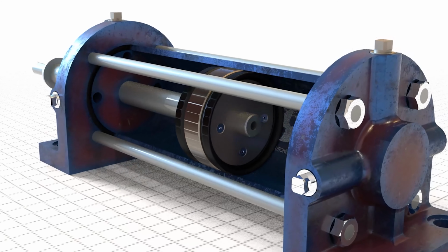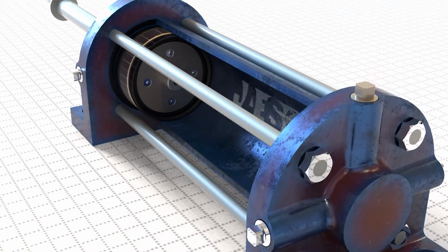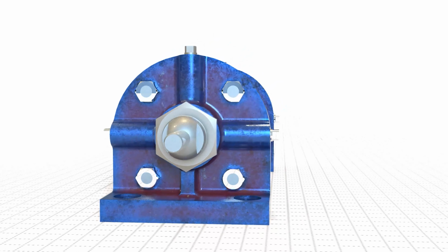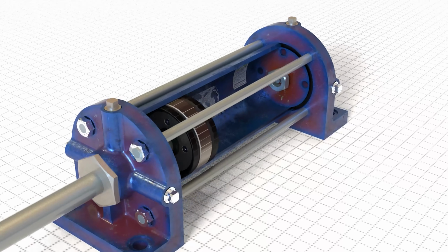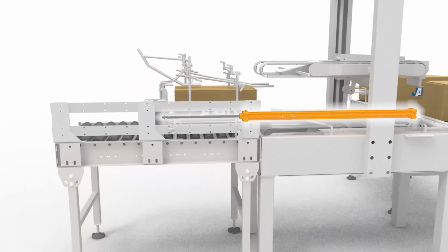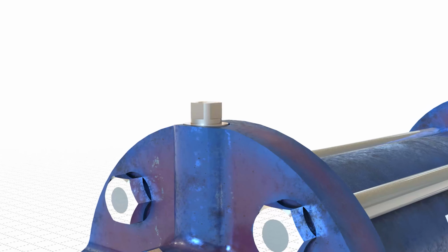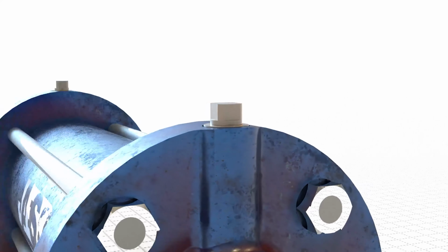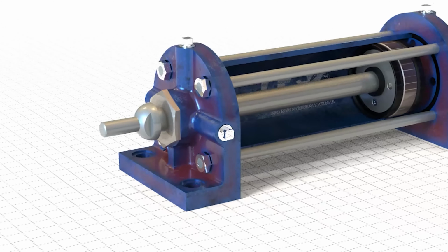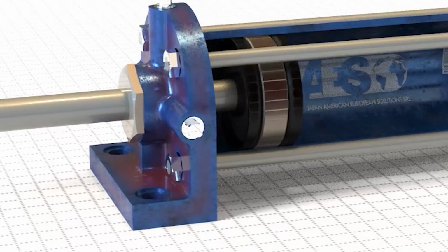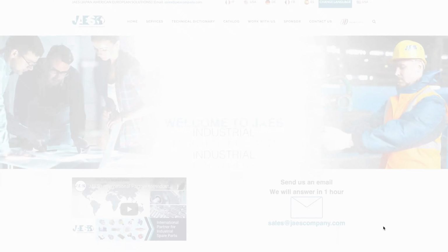Pneumatic systems use compressed air to create rotary or linear motion and power applications. The pneumatic cylinder will use compressed air to act on the piston inside the cylinder to create the required movement. For example, tightening or to move a load along a linear path. A double-acting pneumatic actuator or cylinder has two holes which allow pressure to be applied for movement of the piston in the opposite direction than the one created by the first outlet. Generally, larger is the cylinder hole and greater is the output in terms of strength.